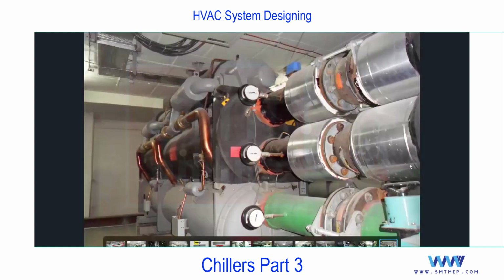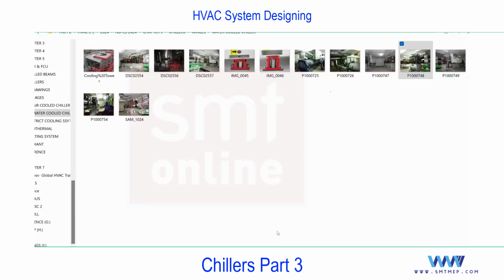These are pressure gauges and different valves. This is very, very important from an interview point of view, and for installation as well as for design. From the design point of view, it matters for pump selection, because all these accessories and fittings will create a higher pressure drop. So that must be considered at the time of pump selection. So as a design engineer or as an installation engineer, these accessories are important for both. So we have a separate detailed topic in part 5. At this level, we're just learning how this system works. Okay, so let me proceed.